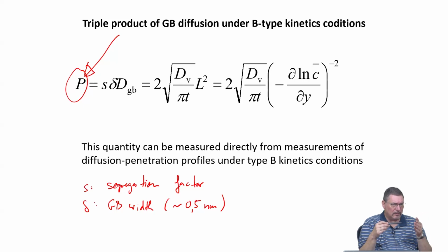And the probability for doing this field evaporation is basically much higher for the highest terraces of atoms than for the lower ones, which means you kind of evaporate first one layer, then the next layer, then the next layer. And since these atoms go through a multi-channel plate, so different holes, and then go to a mass spectrometer, you get chemical identification of the atoms by mass spectrometer, time of flight mass spectrometry.